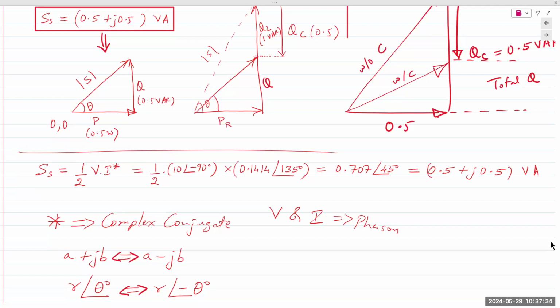Batteries, by the way, are the biggest space occupiers in any mobile device. The reason they integrate the batteries is because they can remove the additional walls around a battery, so they can make it as thin as possible. Now, if your battery is smaller, you can make your device smaller, but then it doesn't last as long, right? So your power requirements are lower, but it doesn't last as long. So there's always system trade-offs. So the bigger the battery you have, the longer it will take to charge, the more power it requires from your adapter.